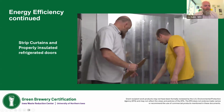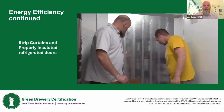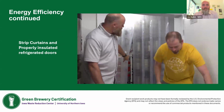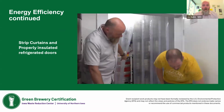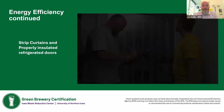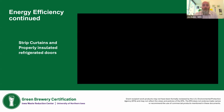An area where a lot of energy can be lost is in the chillers and coolers. They are some of the higher consumers of energy overall. So we check for plastic strip curtains and insulated doors, making sure there's no cold air leaking out of the coolers. And then we'll work with them to help source plastic strip curtains if they can find them, and we'll look at their local utility provider to see if there are any rebates available.